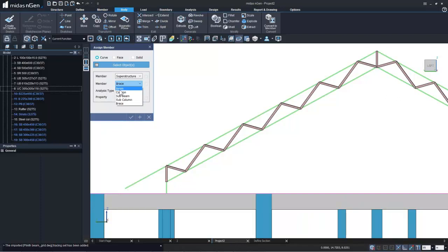Next, for the beams, the top rafter. So top and bottom rafter. So I'm going to be selecting easily using the polygon select. Alright, so whichever I do not want to select, I can simply press shift from my keyboard.